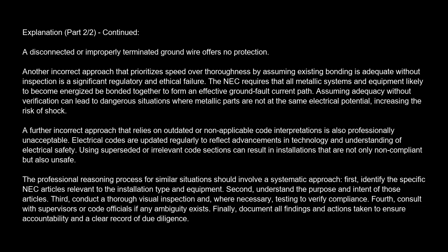Another incorrect approach that prioritizes speed over thoroughness by assuming existing bonding is adequate without inspection is a significant regulatory and ethical failure. The NEC requires that all metallic systems and equipment likely to become energized be bonded together to form an effective ground fault current path. Assuming adequacy without verification can lead to dangerous situations where metallic parts are not at the same electrical potential, increasing